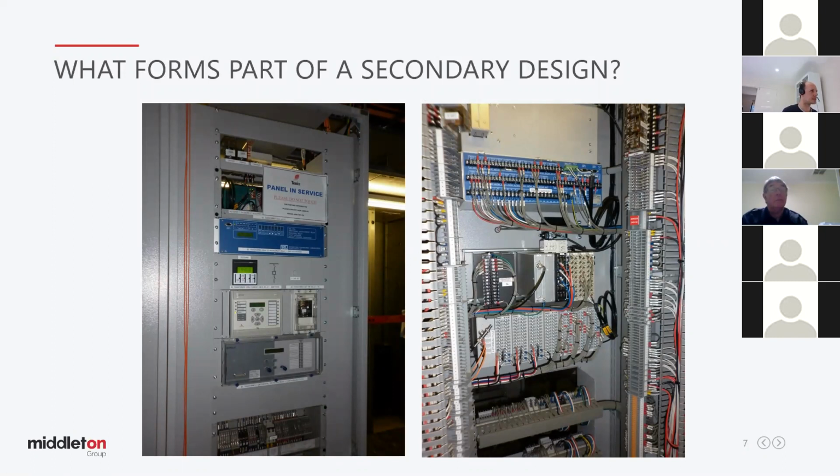So effectively the schematic drawing that we just had on the previous slide, this is a representation of what it might look like in the real world. And secondary design can often be lost, excuse me, lost in translation. And that loss is really down to communication. It helps a lot, particularly when you're a younger engineer starting in the secondary field, to visit lots of sites, to have a look at what equipment is installed at that site, and that gives a greater appreciation for what is in the drawing. So at the end of the day, it's not a drawing. The drawing is just a representation, it's the equipment and interfaces that really matter.